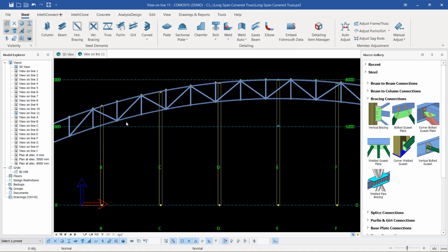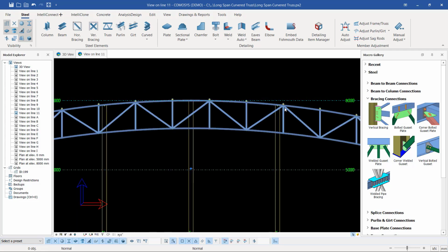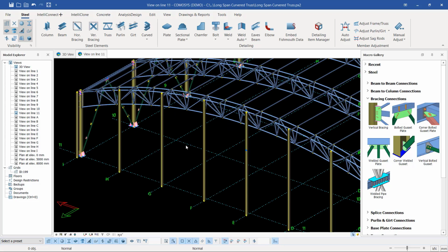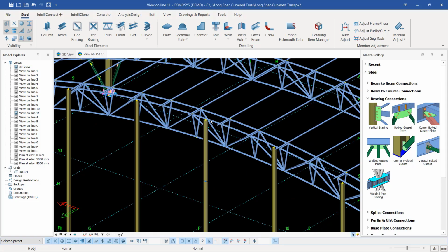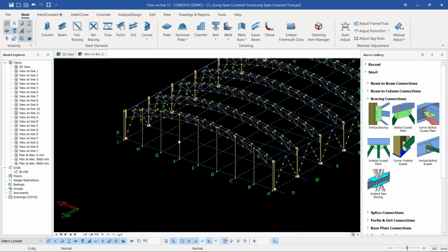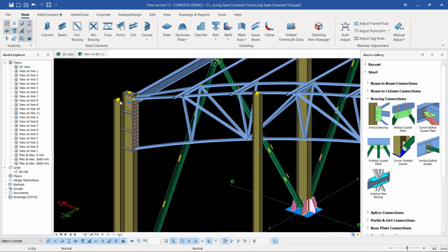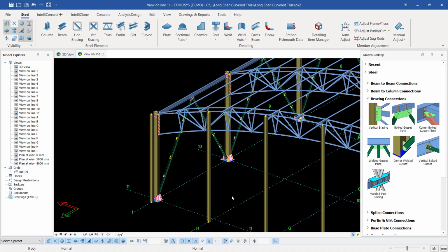So you see on the gable end here, all our columns are reaching the top chord of our curved truss. Now, if I switch back to my isometric view or the model-to-model section, you can see all our columns are touching up here. When we're doing the erection, you want to leave these columns standalone for the longest time, because they start to sway, and you need to tie them together.